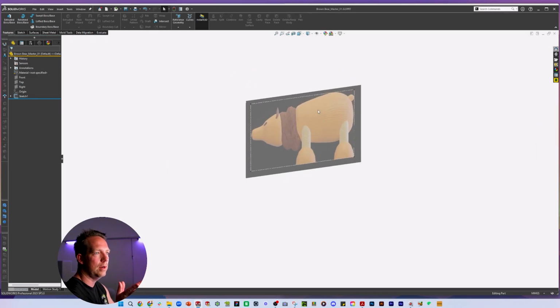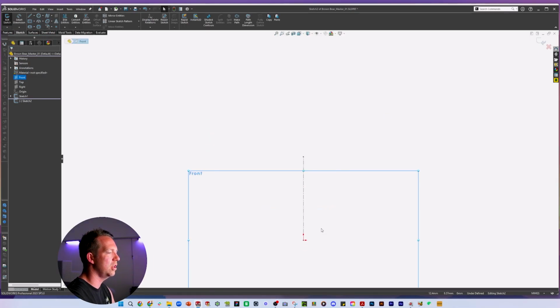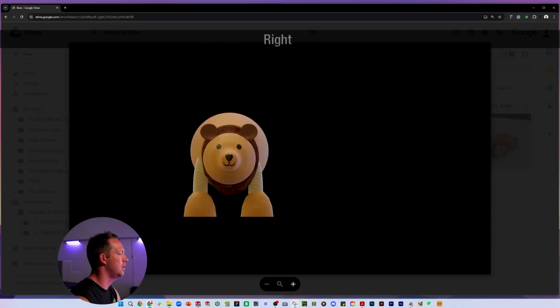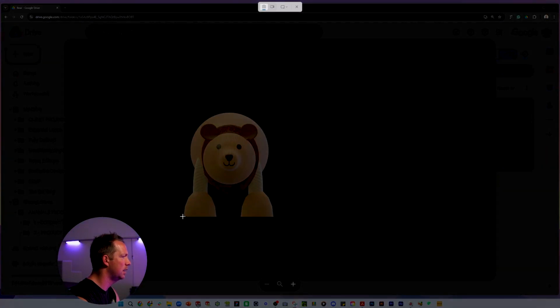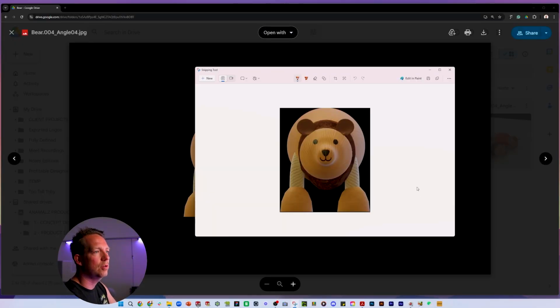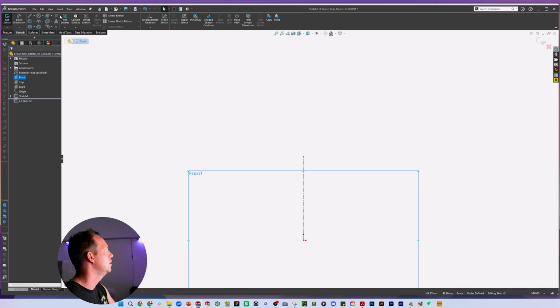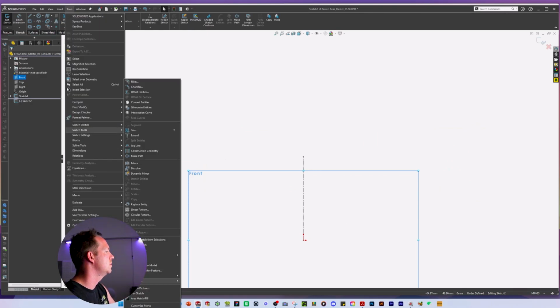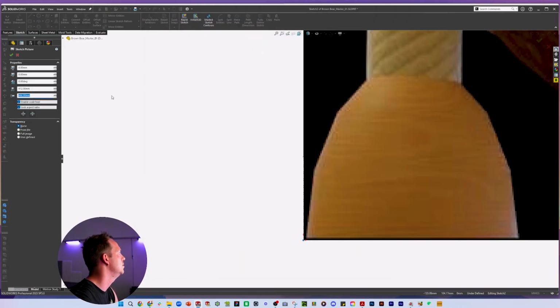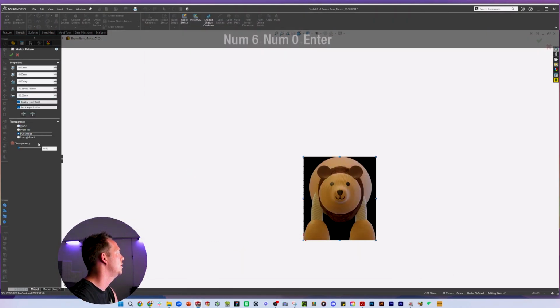Okay. Now, that was the side view. Let's do the front view. And for the front, we're going to do the same thing. Now, we've already got that sketch line, so we don't need to do another box. I did have to start a sketch, and I do need to go back into here and get this front view. Now, what I can do this time is actually trim right to the corner and right to the top. Okay, so that's the image that I've created. And once I come back in here, I'm going to go Tools, Sketch Picture, find that screenshot, open, change the height to 60, change the transparency to half.